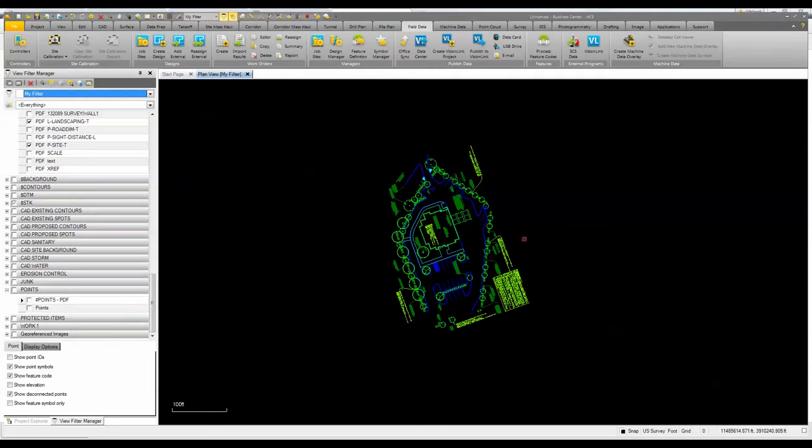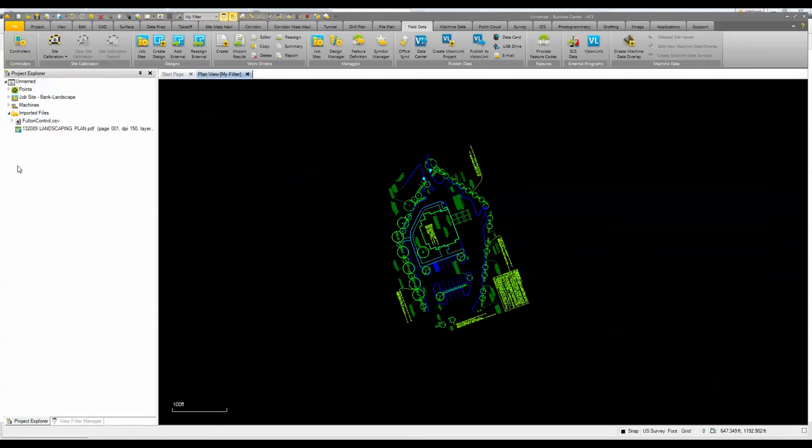So basically what I've done is put this together and sent it out to a controller, and that controller would be synced to my computer. Or we have a remote setup where you can send this out and sync it through our Trimble Connected Community, and send it to a guy who may already be out on site somewhere or on another project, and you want him to stake out this vegetation. So he doesn't have to come back to the office. He can do this remotely.